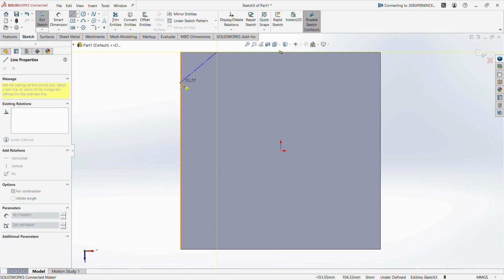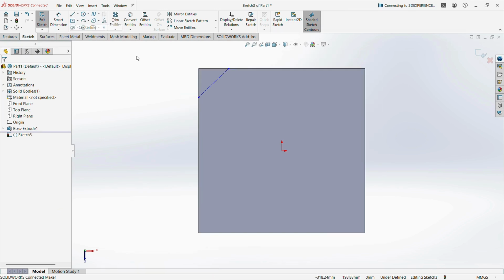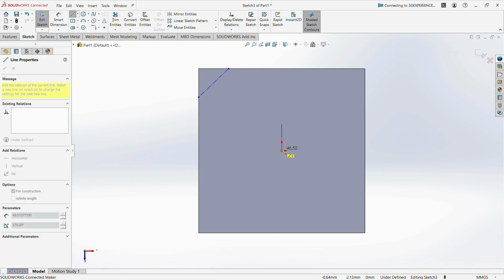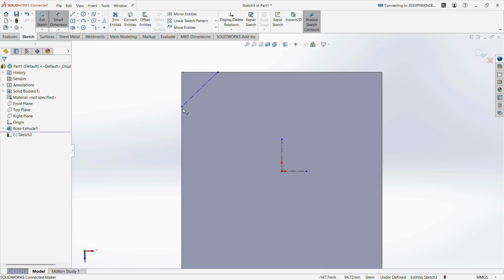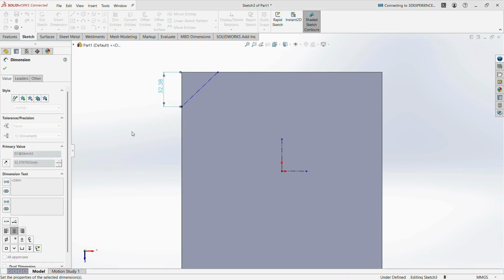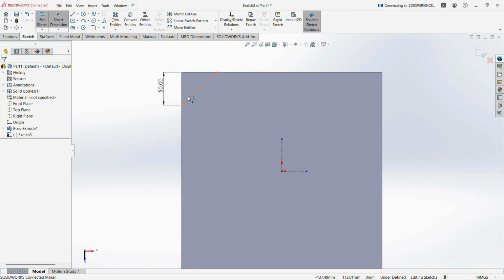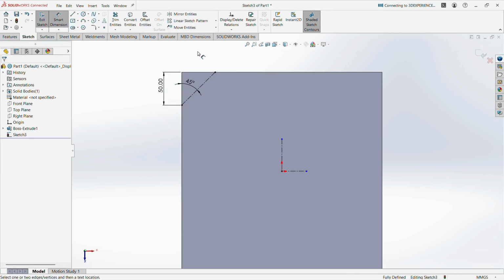based on this angular line. Once we draw this particular line profile, then fix this up to the recommended dimensions. So using smart dimensions, fix this profile. Afterwards, from this reference line, we are going to mirror it to all four different corners. What is the specified dimension value? It is 50 mm. Then the angular dimension is 45 degrees.